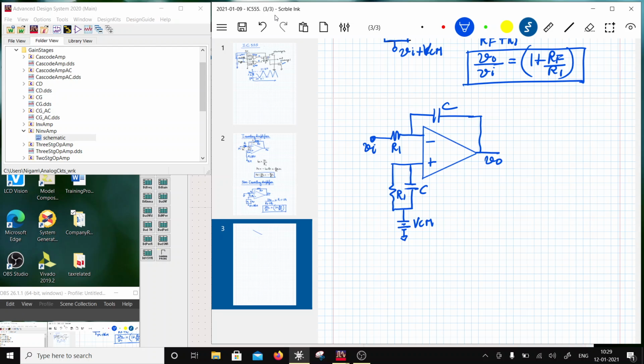Fine. So what's going to happen is, this is a small signal 0. So this is small signal. So the current is VI over R1. So this is your IN. And then there is a capacitor which charges this A. So I assume that the initial charge on the capacitor is 0. So I have 1 over C integral I dt. I is going to be VI over R1 times dt, and this will be equal to VO.